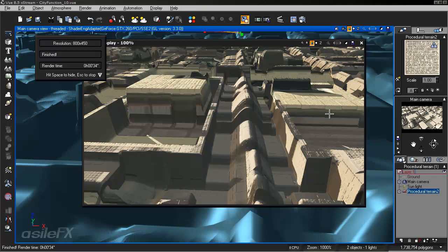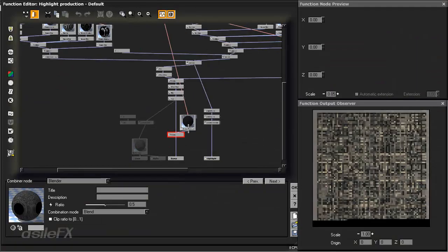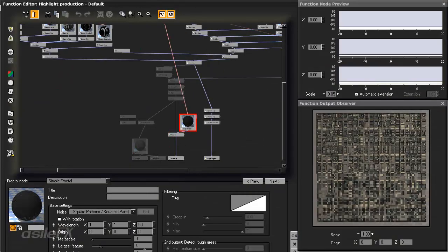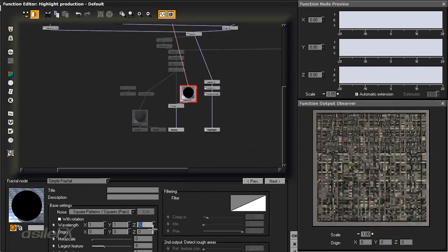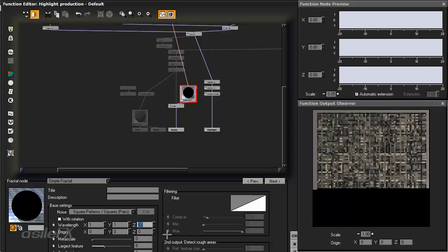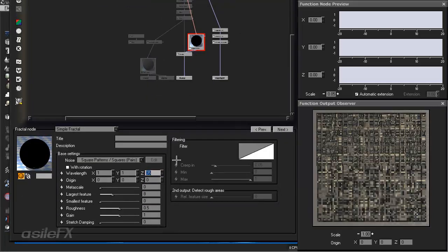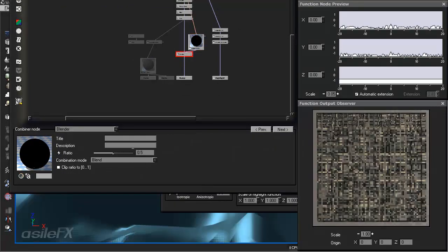So I will do one thing, which is to increase that scale, because I thought it was a little bit small. So take that largest feature, and I'm going to bump it up to 8. I'm also going to reduce that Z-scale to, say, 35, because I thought maybe that was stretched a little too much. And the gain, I'm going to set to 1.5. And the blending, let's use a 0.25. So just a small blend,